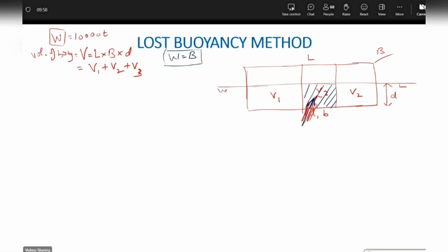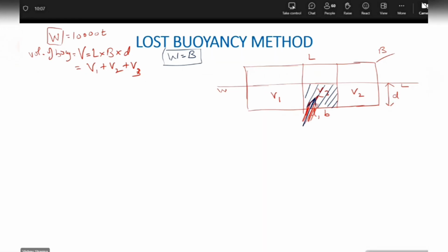It will change. Why? Because the level inside has to be the same as the draft outside, and when the vessel rolls or pitches, the draft at that compartment location will change, causing the level to change. If the level is changing, what is happening then? If the level is rising in the compartment, that means more seawater is coming. If the level is dropping, that means some water has gone out to sea. That's how the level will change.